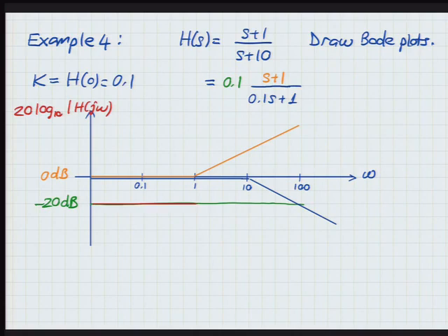What happens from 1 to 10? I start going up. The orange line wants to move me up by 20 dBs in 1 decade. The blue line is doing nothing, so I go with the orange. So I go from where I am, which is negative 20 dB, to 0 dB, right? And what happens after? Now there's a battle between the orange and the blue. Orange wants to take us up by 20 dBs. Blue wants to pull us down by 20 dBs. What do? We don't move. We stay flat. All right, so afterwards, we just decide to stay flat.